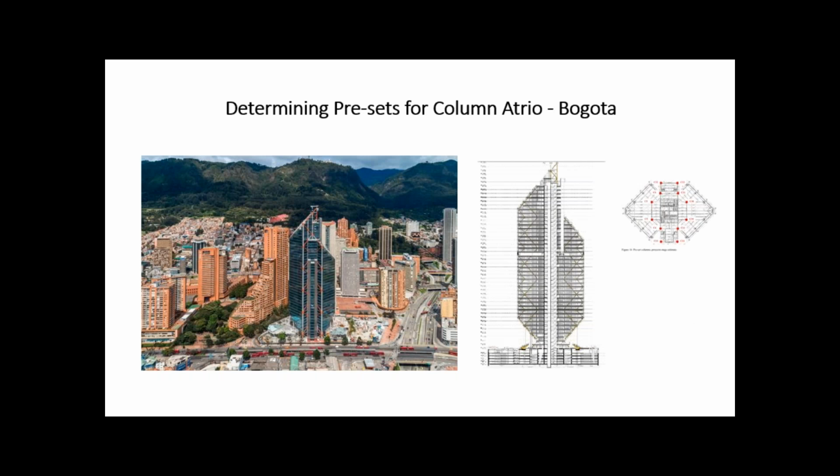This is the project that Station and I worked on for about 3 or 4 years in Bogota, Colombia. It was designed from an architecture by Rogers and Stirk in London, and the structural design was done by Arup in London. It's a 46-story concrete core and perimeter exoskeleton. One of the critical criteria for performance was to ensure that the floors would be level and flat, allowing for the loading and movements of the core relative to the steel and the concrete columns around the perimeter.